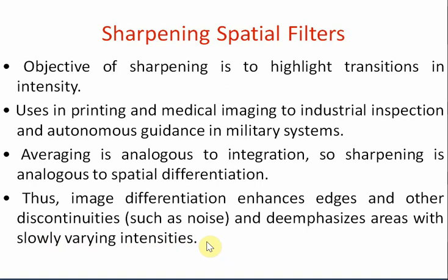Other discontinuities also means maybe noise. That means in addition to enhancing the desired edges, it also enhances some undesired edges. Those are said to be noise. So differentiation enhances the noise. And it de-emphasizes areas with slowly varying intensities, which reduces the effect on slowly varying intensities. What is the conclusion here?